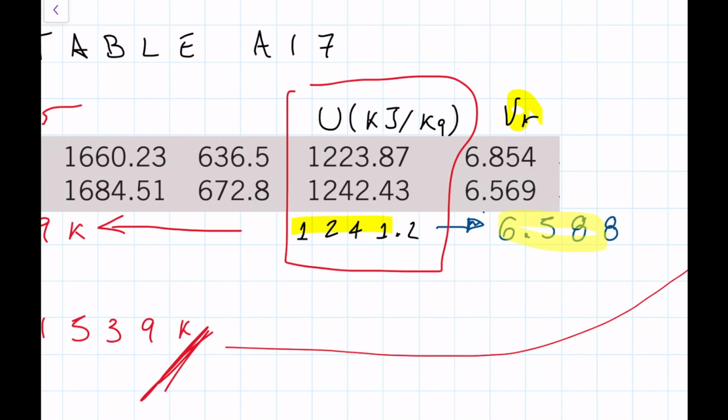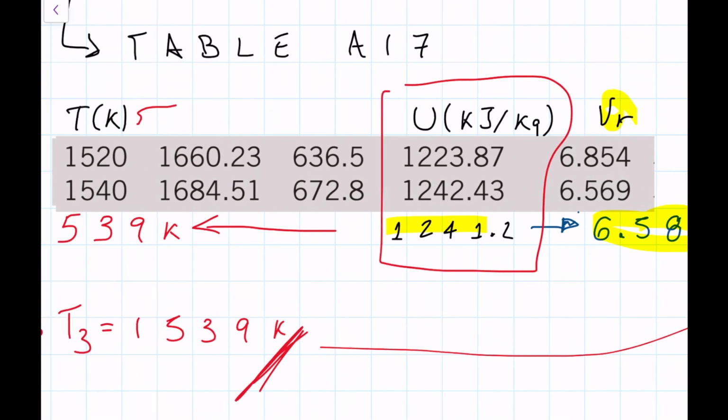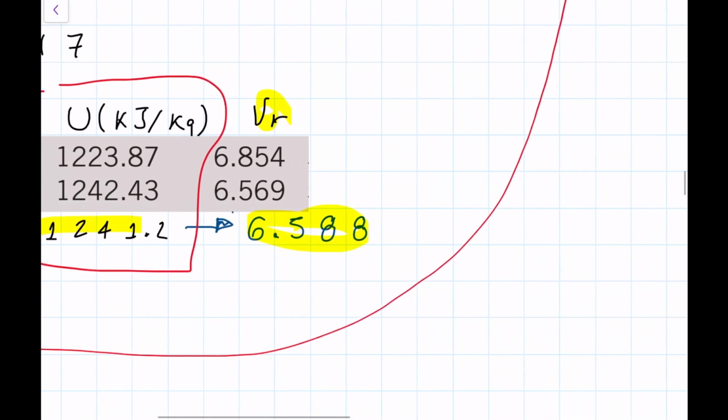relative specific volume 3, because I'm going to use that to be able to solve for 4, right? Because we know from 3 to 4 it's a nice isentropic process. Okay, so I already grabbed that ahead of time. But now what I'm going to do is take this T3 that we just found, and plug it back into our P3 equation so that we can solve for P3.